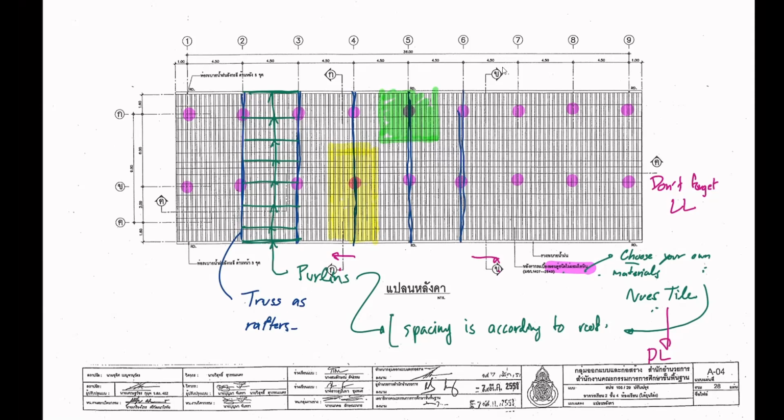Keep in mind that you need to have a good draining system. Otherwise, you must include this kind of load in the design of your concrete roof. Simple as that. Sometimes people will be crazy enough to have a garden on the roof, so you must include the weight of the garden when you design the roof.